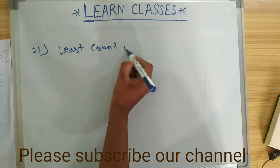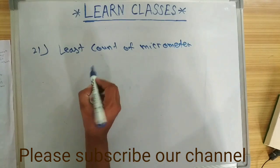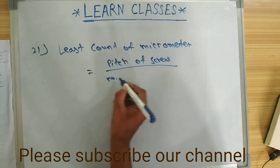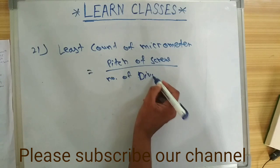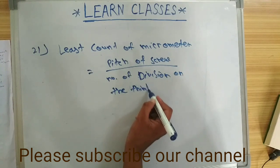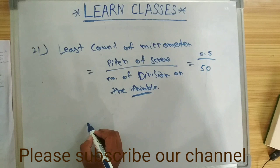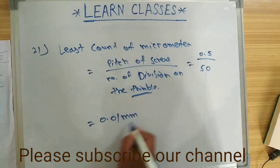Least count of the micrometer is equal to pitch of screw divided by number of divisions on the thimble. Generally, pitch of the screw is 0.5 and the number of divisions on the thimble is 50, and least count of micrometer is 0.01 mm.